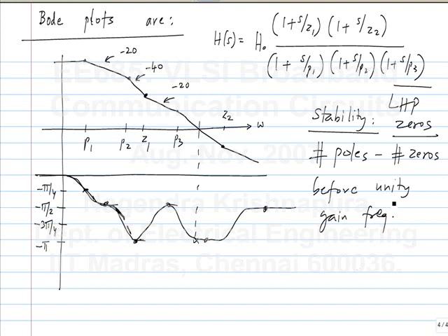That is the exact criterion, that the roots of 1 plus L should be in the left half plane. That is the criterion for stability. There are many approximate things that we use which hold under restricted conditions. Usually, the conditions are not stated, but in this case, this is true only if the poles and zeros are both in the left half plane. You can have many poles and zeros, but the number of poles minus the number of zeros can be 1. It can't be more than 1.